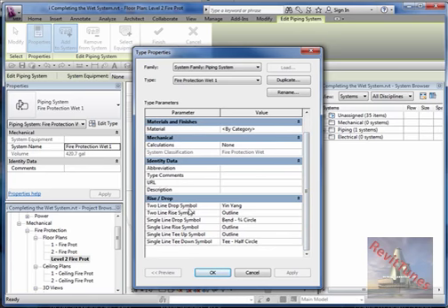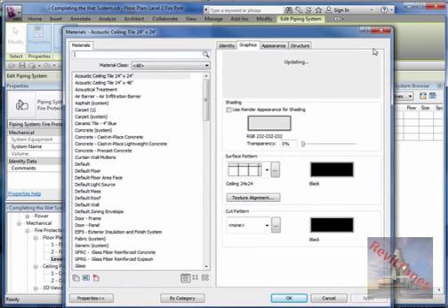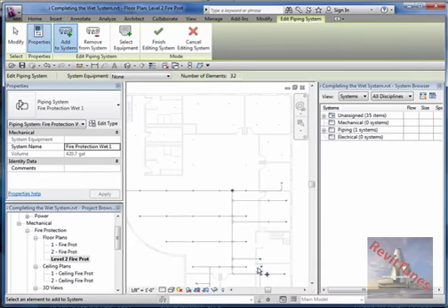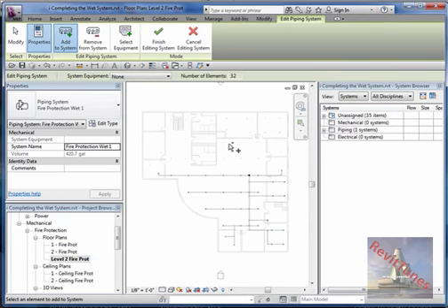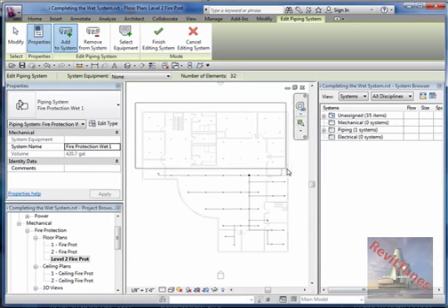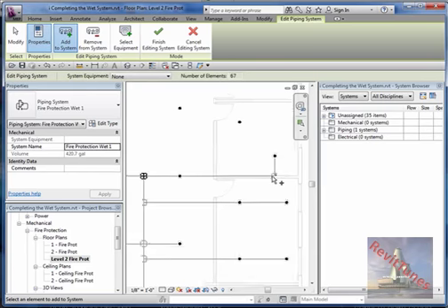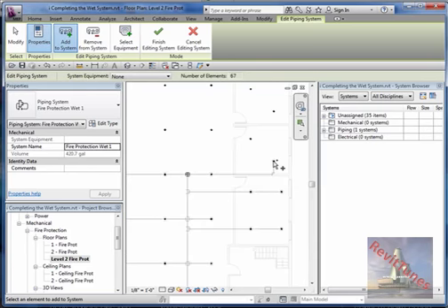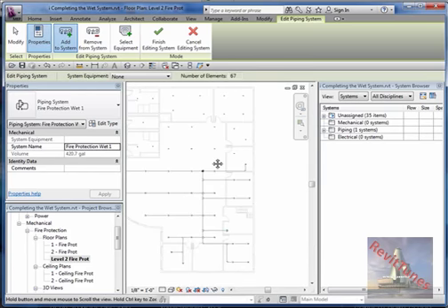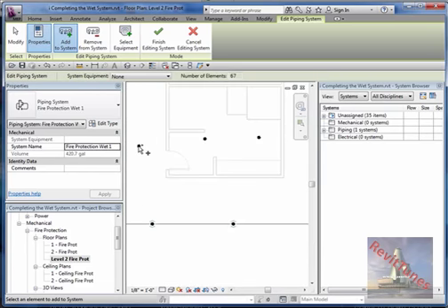In this case the symbology we use is standard symbology. I'm not gonna change anything here. And material by category, but you could also start going more in detail and choose the appropriate material, but I'm not gonna choose material. Okay, so I wanna hit add because I want to add more sprinklers, and I could do just a window. And notice that even if I pass to where I already had included those sprinklers, my window covered those also. It doesn't matter. Now it's giving me all those new ones.